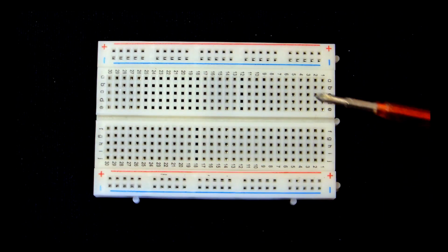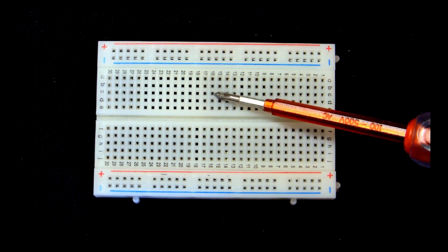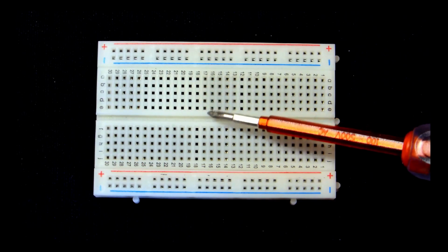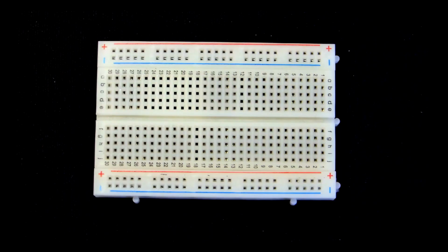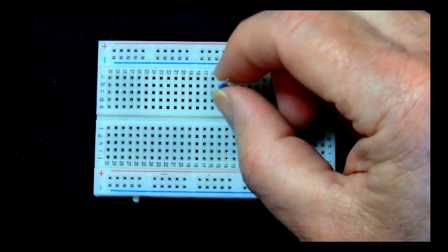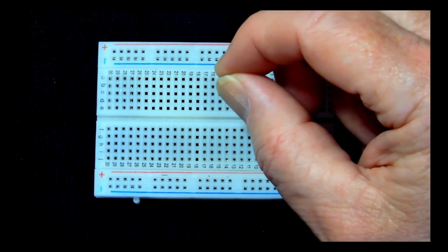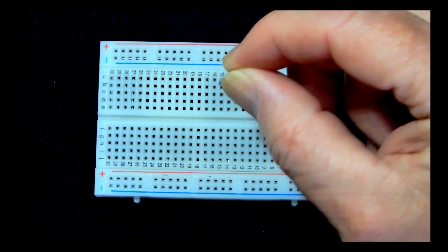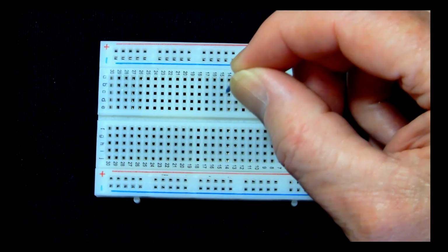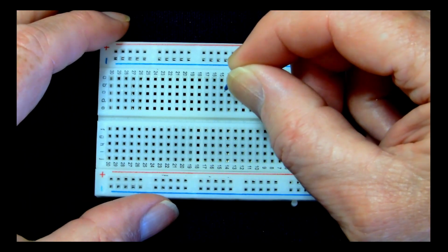If you look down the holes, you should be able to see the opening of the sprung connector that you push the leads through. That's what we're looking for. If they look blocked, then you may not be able to get your cable in there. I would say 15, third one down doesn't look very good to me. So let me poke something in it. Well, that's weird. Look at that. I can just pick that up and the board just drops off it. So that's telling me straight away that there's something wrong.